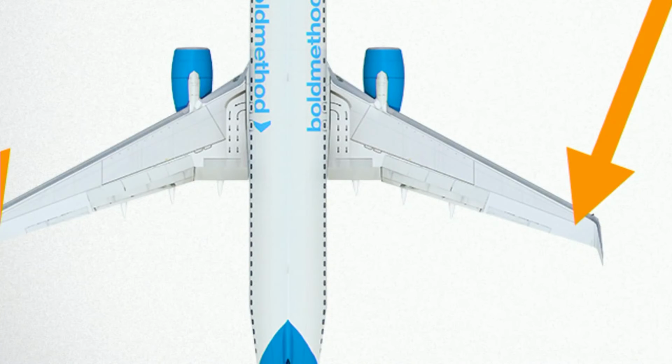So it's going to have a much higher stall speed if that wing was clean. The other problem that you run into, if you take a look at this again, is all of that spanwise flow starts to pile up. You would think that it's kind of innocuous, but it isn't. What it ends up doing is it thickens the boundary layer right here. Essentially, it removes energy from the air at the tips of the wings.